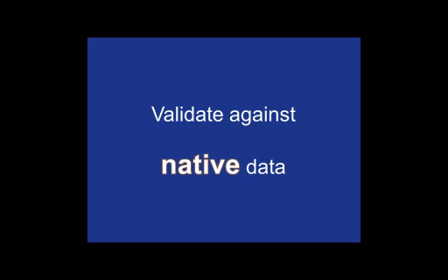So the first takeaway is validate by referencing your native CATIA data. By virtue of operating natively in CATIA V5, there is no data translation. The CMM program is fully associative to the 3D model. So for example, if you change a hole location, the CATIA V5 CMM Planner that we'll be showing you today will automatically update the CMM program to reflect the changes.